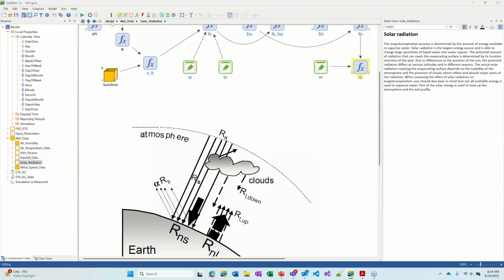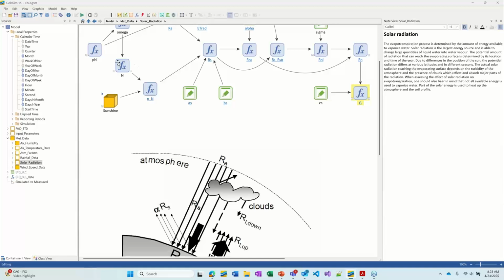And that's where, going back to the inputs of the model, one of the things we needed to input was the daytime sunshine hours. And so that's out of a 24-hour period, how much of that would be sunshine? And so we have just daylight hours, and that's N. This just depends on where you are on the planet. But then we reduce N by determining cloud cover throughout the day. So for example, in the Seattle area where I am, our numbers would be smaller than, say, in Phoenix or in a desert area.